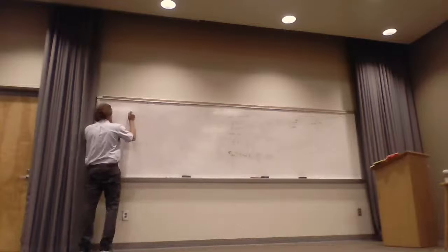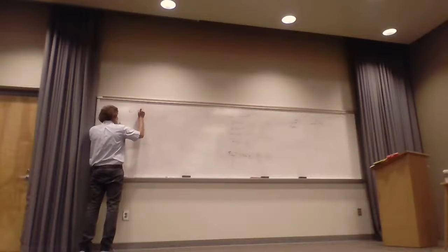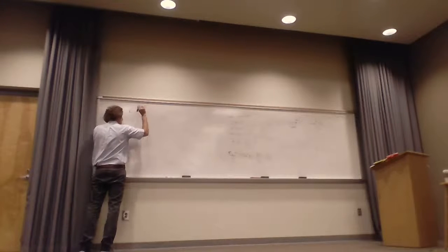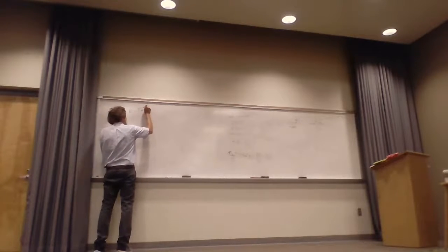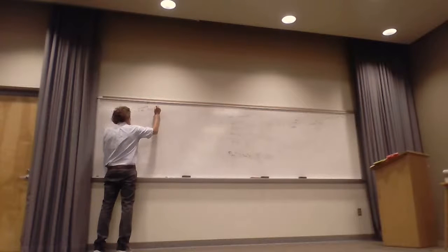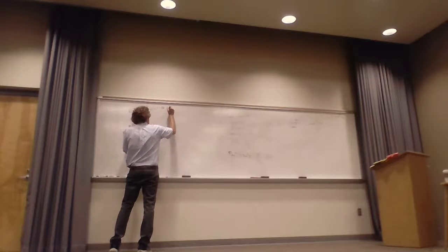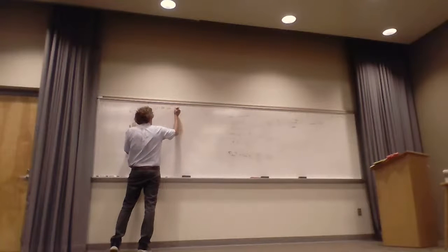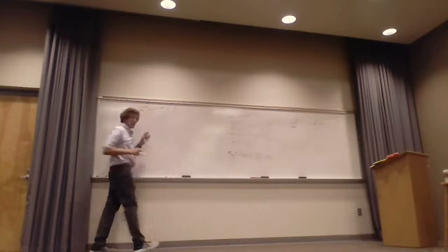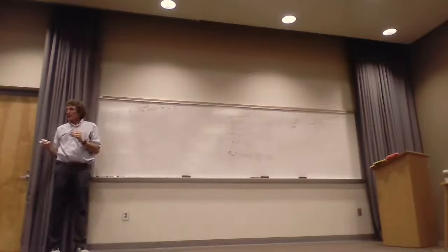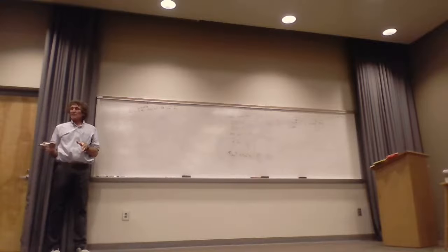I know that the E field is a propagating plane wave. The E field in the actual time domain was 5e to the minus alpha z, I'm just going to leave it as alpha, we calculated that, times the cosine of omega t minus beta z, right? And it's times 10 to the minus 3rd, and it's in the a_y direction. Correct, class? Now, that is in the time domain.